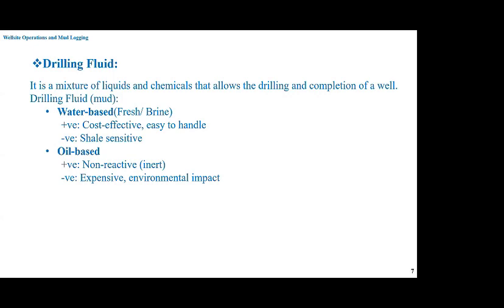For water-based mud, they may use fresh water or brine water to mix the chemicals. The advantage of water-based mud is that it is cost effective because we use water, either fresh or brine, so it is less costly, and also it is easy to handle. But the disadvantage of water-based mud is that it is shale sensitive, especially in areas of reactive shale, which reacts with the water and causes operational problems, as you know, stuck problems, mechanical stuck, and that leads to more complication of operations.